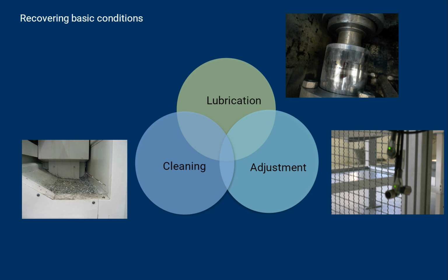When steps 1 and 2 of autonomous maintenance are developed, the effects on the results are truly extraordinary. By eliminating more than 70% of anomalies in 1 year, maintenance cost reductions of more than 15%, or improving overall equipment efficiency, OEE, by more than 10% can be achieved in a pilot area.